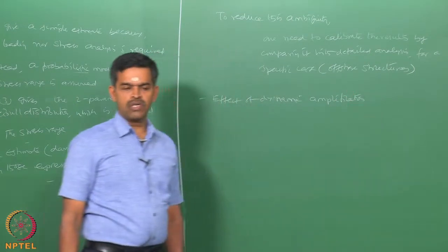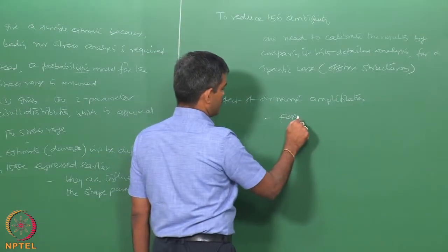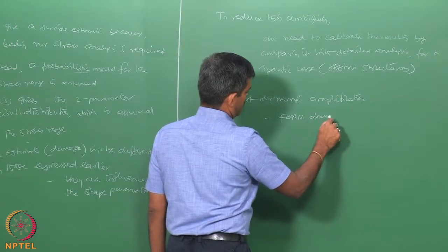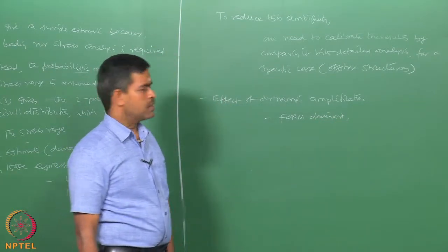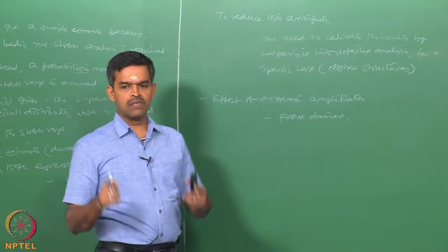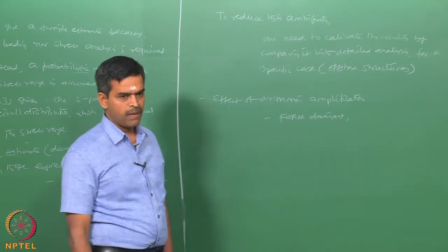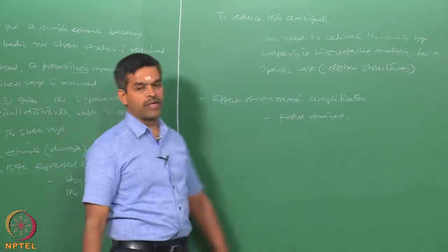In case of offshore structures, where essentially they are form dominant, there is always a possibility that the dynamic response may get amplified at certain frequency bands, because systems are actually designed to remain positively buoyant.